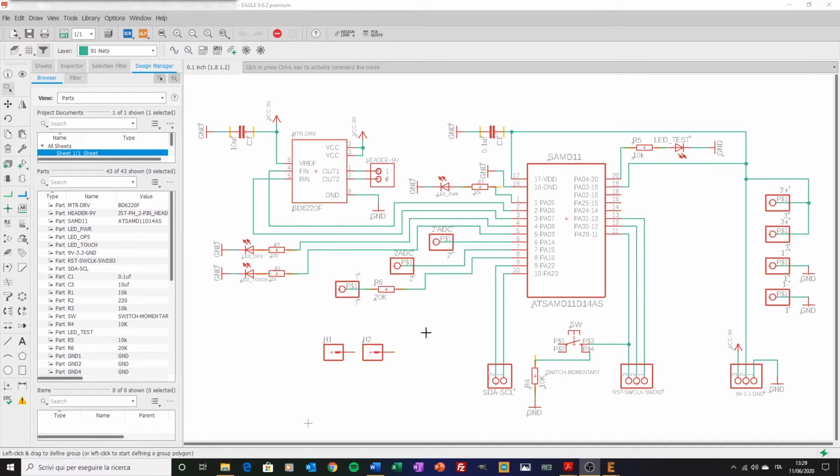Finally, there is a last through-hole connector here for the capacitive touch feature, which is wired to PA16 here on the MCU via a 20K resistor. This pin is implemented in the PTC channel, where the PTC is the capacitive touch device inside the SAMD11 MCU. Moving on, we have 3 groups here and here of headers for power supply and connectivity of the board with the outside.